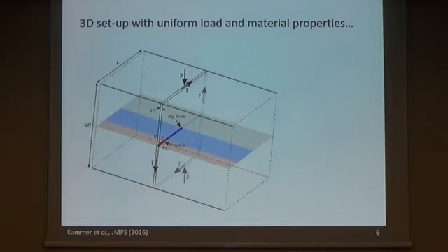We have a three-dimensional setup. This is finite element simulations. It has millions of degrees of freedom that we use in order to be sure that everything is mesh converged. We simulate two blocks. The top block is this block over this length. We have a bottom block over here. What is in color is the interface between the two blocks. It's infinite in this length, so out of this area, infinite. The loading looks a little bit weird, but what we do is we have a finite system, but the loading is applied so that we have uniform loading in the finite system.